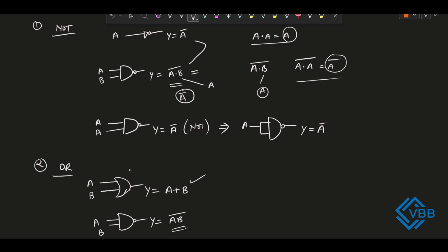So first we will observe this and try to get the OR gate expression from this expression. There is one method, or we can say one theorem, De Morgan's theorem. It says that if there is the whole complement of two or more variables, then we can expand this into OR form, A bar plus B bar, like that. This is nothing but De Morgan's theorem, which you also need to keep in your mind during the NAND gate implementation.